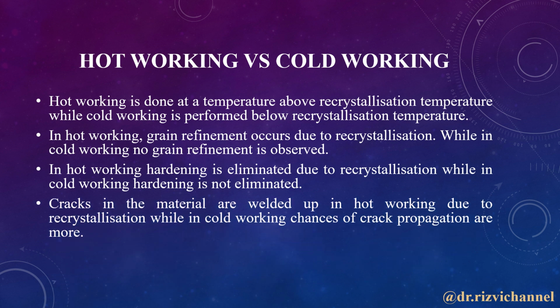If there are cracks in the material due to hot working, newer grains are formed and all the previously existing cracks are welded up. But in the case of cold working, as we are working below recrystallization temperature and no newer grains are formed, so crack propagation is more and the chances of crack occurrence are more.